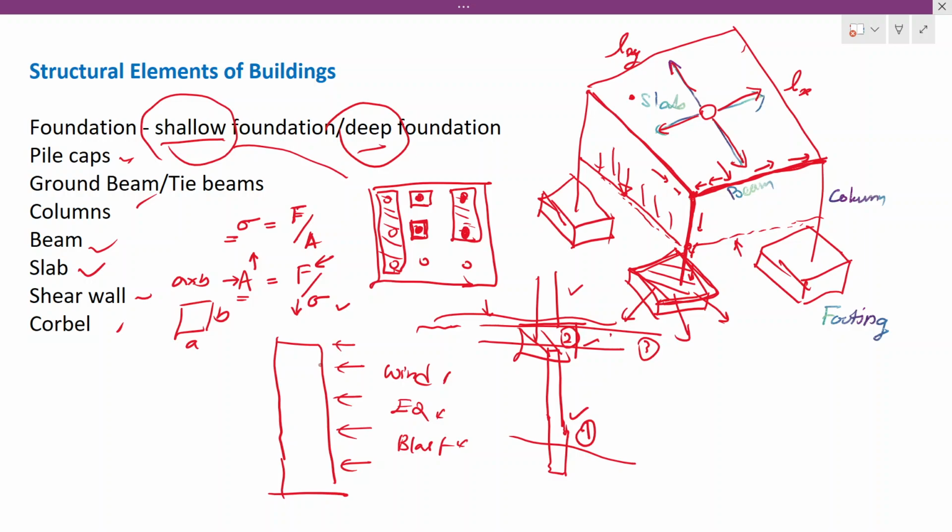So when you have a wind load on a tall structure, there will be a very high bending moment on the foundation. So we have to control it, otherwise this column-beam frame structure has to bear this load. It will be very difficult, because we might need very large elements. But what we can do is introduce shear walls in a structure like that, right?